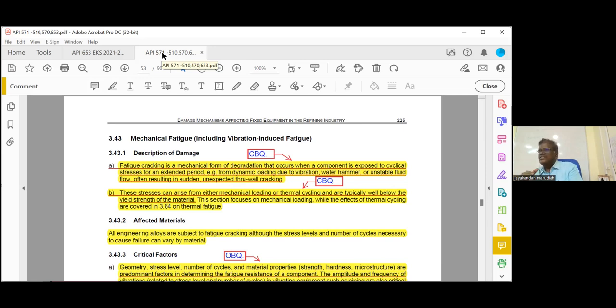When you remove the stress, if there is no strain, then it is called elastic. If you are giving load, pulling, the dimension changes, and when you release it, it goes back to the original dimension. That is called elastic. All materials will behave like that up to a certain load. But when a certain load is exceeded, even if you remove the load, the deformation will be permanent. That is called plastic. So generally, engineering material like steel will not fail below yield stress. It will fail only above the elastic range, in the plastic range.